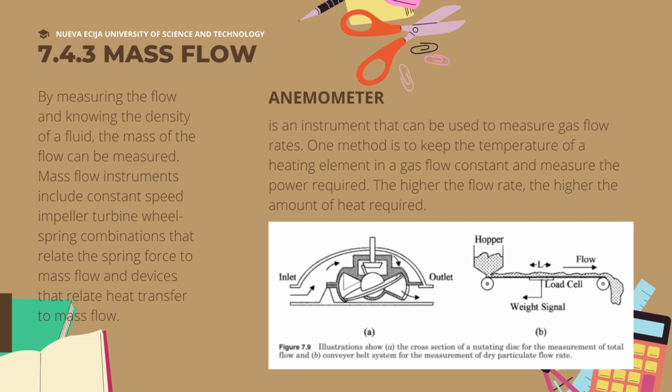Micro-machined anemometers are now widely used in automobiles for the measurement of air intake mass. The advantages of this type of sensor are that they are very small, have no moving parts, pose little obstruction to flow, have a low thermal time constant, and are very cost effective along with good longevity.